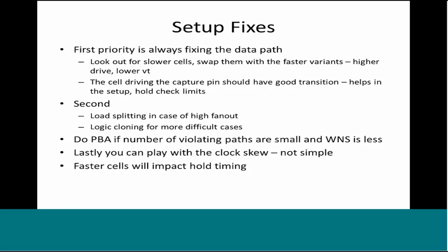Splitting the load and logic cloning are somewhat similar in nature, but logic cloning can involve more than one cell. It can involve cloning even a block. So again, it's an advanced technique. It is not done easily. You have to do a lot of checking in PrimeTime. You have to check a lot of reports before even attempting this.